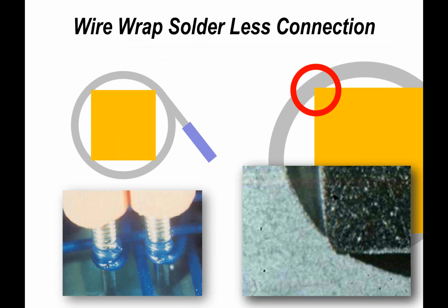But there was a lot of debate in the industry about whether you needed pins and wires which were square with sharp corners and didn't have any solder on. If you actually had pins with solder on, yes, the indentation may be less, but the actual pull-off force by which we would qualify and test a process would really not be affected. In fact, it would be a higher pull-off force. If you did contact resistance, you wouldn't see any difference. And even after environmental testing, temperature cycling and aging, you really wouldn't see a difference. So this is one of the ways in which our company went in a slightly different direction to 2 of our competitors back in the day.